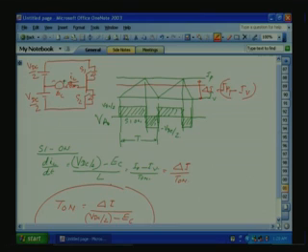Now, let us take the T off period. T on we have found out. So, let us go to the T off period. T on we can write here: delta I by T on is equal to VDC by 2 minus EC, divided by L. Okay.